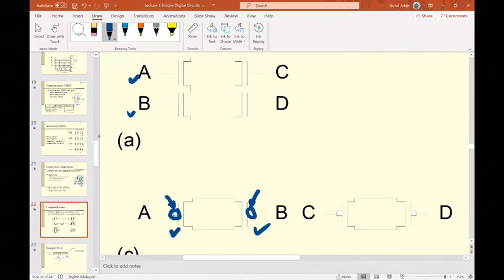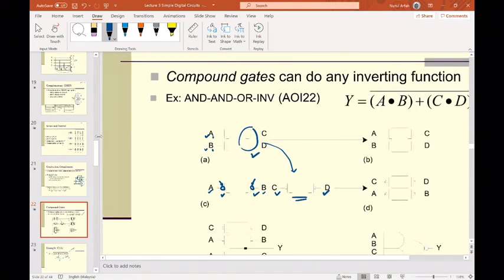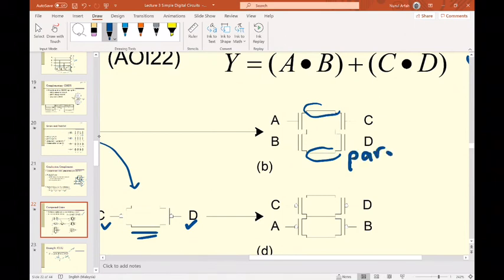You have a bubble here. And this is A and B. So you write down the first gate is for A and the second gate for B. And then same to this side, you have C and D. Since they are in series, you should do the opposite thing for PMOS. So they are in parallel. Okay. And then now you have this. The next step is for this part, you do the connection of parallel, right? So in our PMOS, this is parallel.